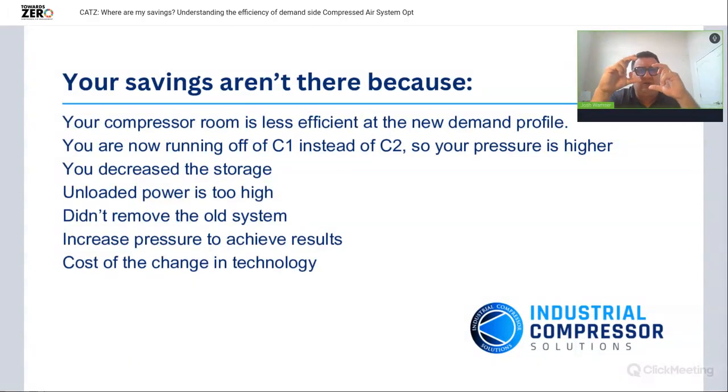If we're running two compressors in a cascading pressure band, well, when we're running that second compressor, our pressure is lower because we're operating below the pressure set points of the first compressor. When we shut off compressor number 2, pressure comes up, and now all artificial demand, leaks, and waste are being overpressurized, depending on our pressure control.